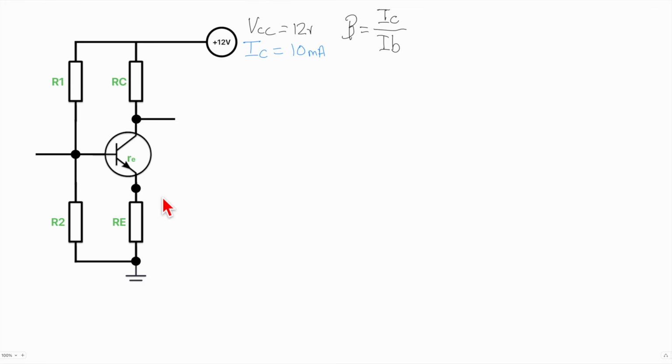The only difference is, of course, the current here will be in phase. Here it will be out of phase, 180 degrees out of phase. So when we come to putting an AC signal, the peaks here will correspond to the troughs here. But that's not the case at the emitter.